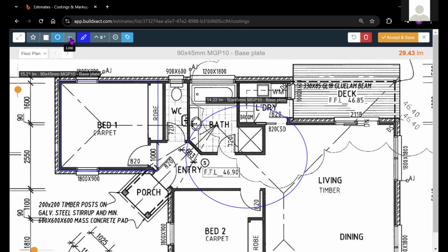The line tool in this case will just measure a straight line, whereas in square meter takeoffs, we were entering in a height. With lineal meters, it's just literally measuring a line. Similarly, we've also got the ability to change our drawing color, the ability to measure linear meter takeoff with a pitch, as well as the ability to draw deductions and to turn the labels on and off.